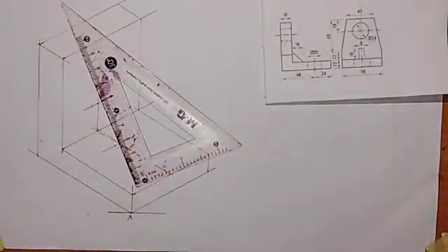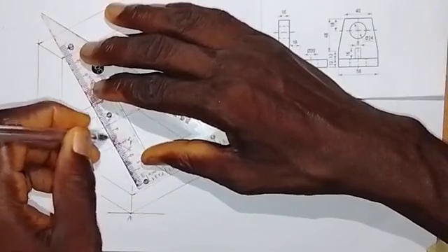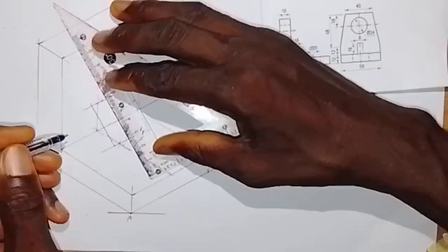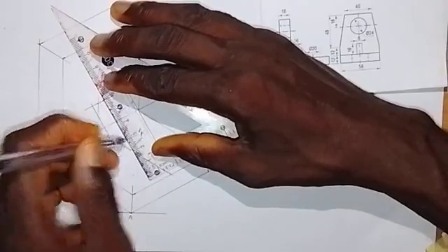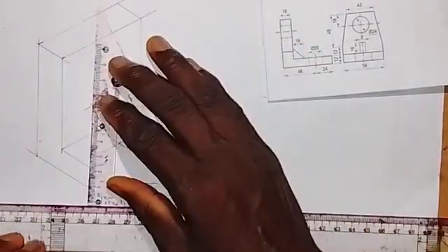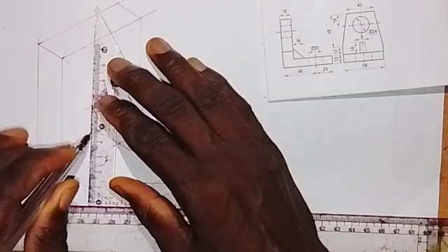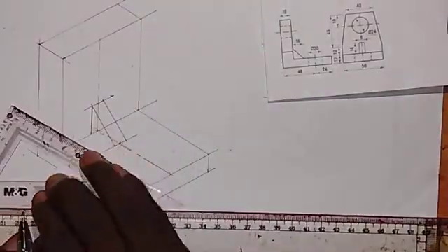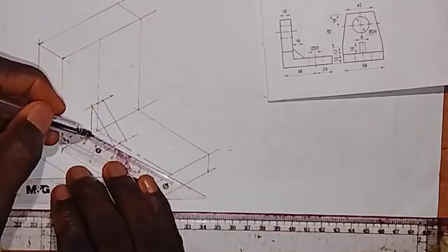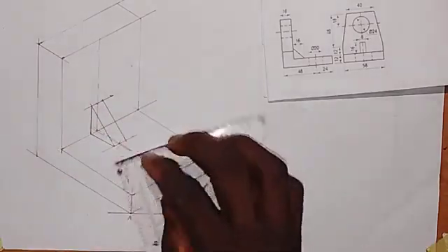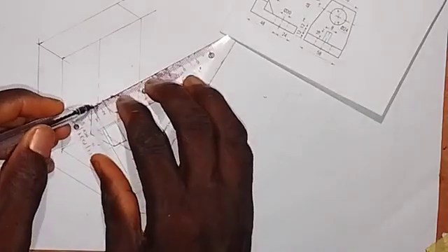So we are going to join this together, making it a thick line at once. Join this together with this, like this, and then we come here and join this together with this. So we have this now. What I'm going to do here is draw a vertical line from this point, making it a thick line at once to touch this. Then with my 30-degree set square, I will join these 2 points together like this. So the web is already there, as you can see in this diagram. We have the web in place already.